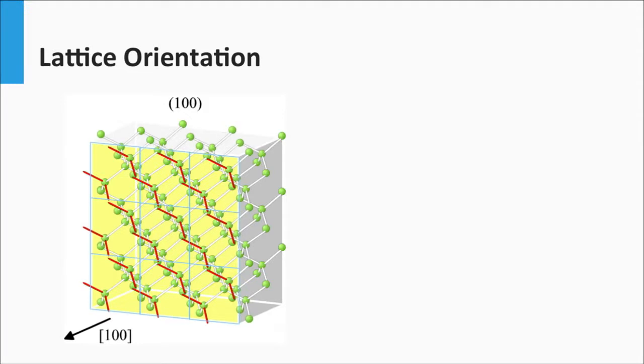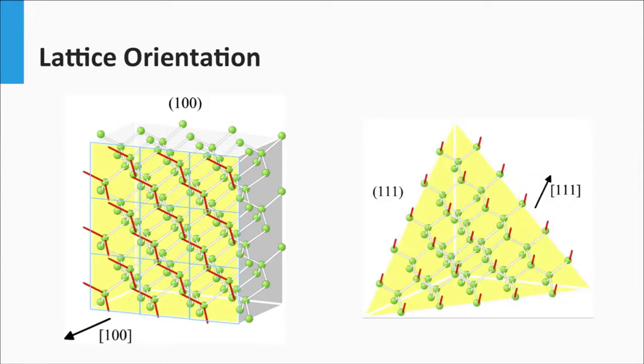The silicon at the 100 surface always has two back bonds and two other valence electrons pointing to the front. The second surface is the 111 plane. It can be characterized by 3 silicon back bonds and 1 valence electron pointing in the normal to the plane.